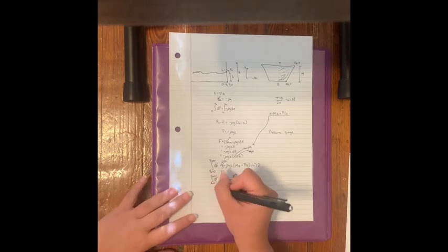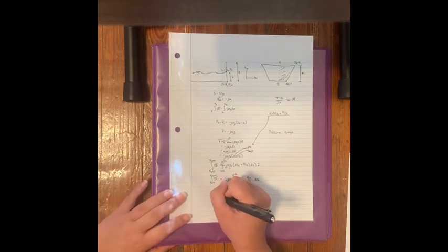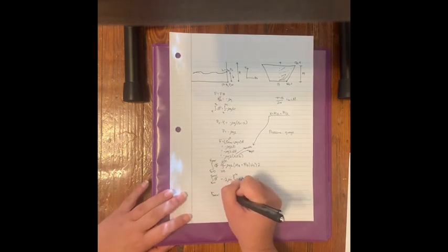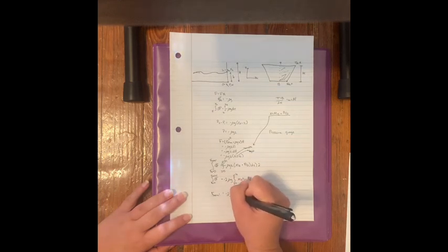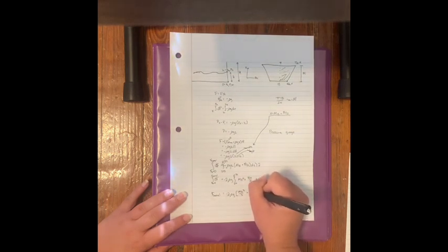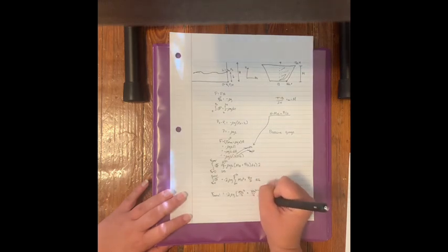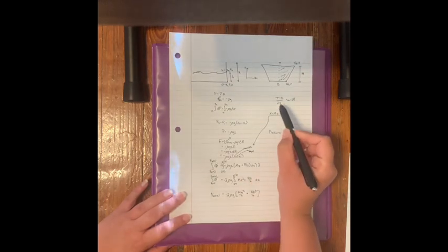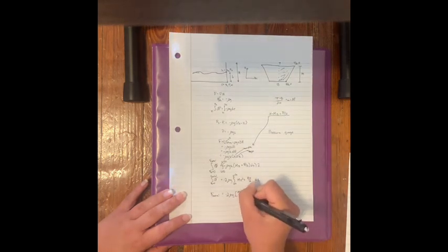So when we integrate that, we get that our total force will be equal to negative 2 times the density times acceleration due to gravity times the quantity M, h, little h, which is the height of our water, cubed over 3, plus the bottom width times the height of our water squared over 4. We aren't done yet because we still need to substitute this expression back in for M.